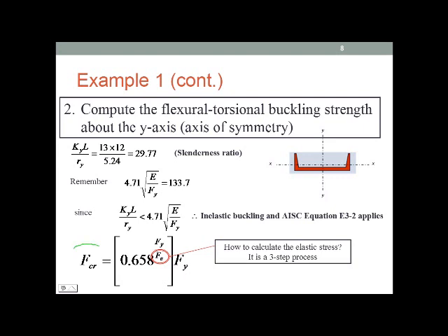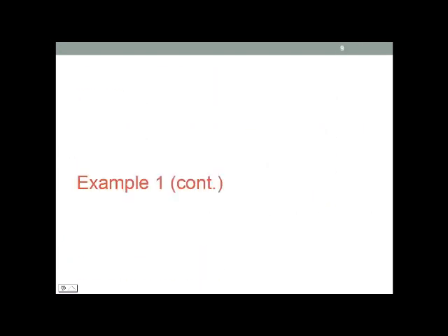Now we are ready to calculate the critical stress. The critical stress equals 0.658 to the power Fy over Fe, the whole thing multiplied by Fy. The question is how to calculate the elastic stress Fe. It is a three-step process.